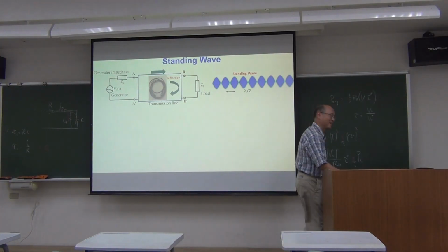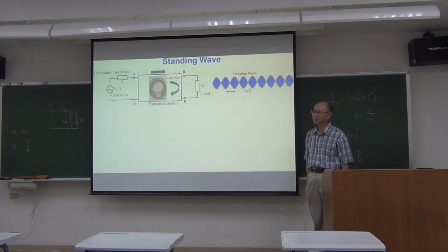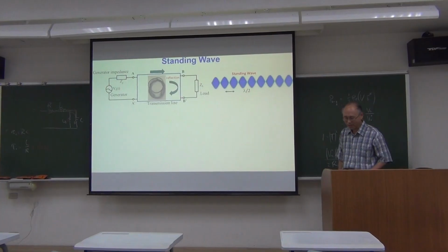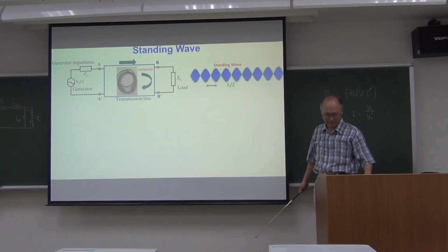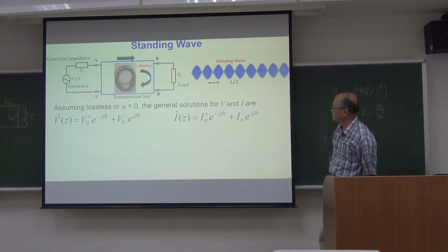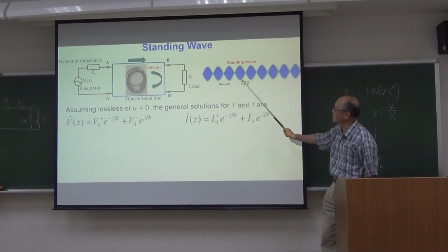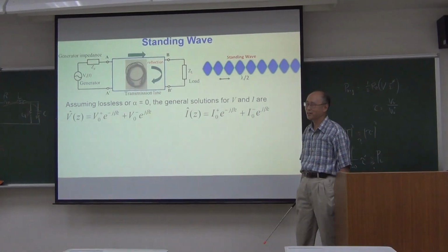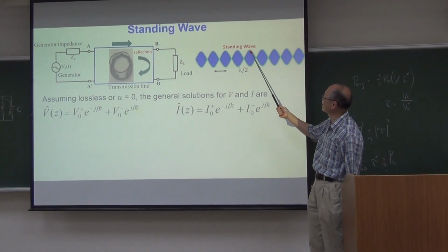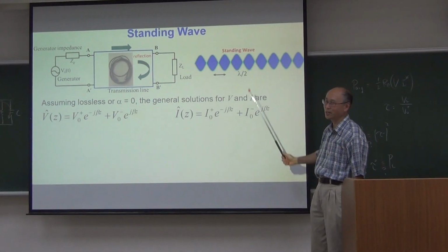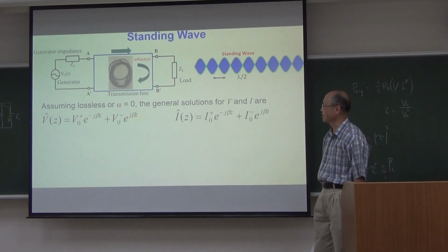Okay. So you have standing wave in this transmission line. Okay. But I think on this Wednesday I can do a better job. I'm going to get the notes straight. Right. So this is a complete reflection at the end of this transmission line. Therefore, you have complete destructive interference and 100% constructive interference. Okay. And you have the 100% contrast.